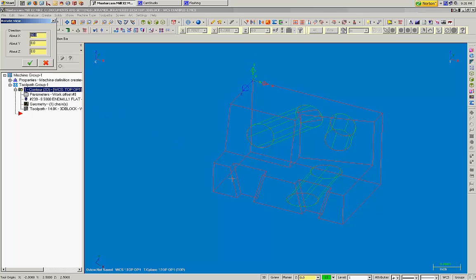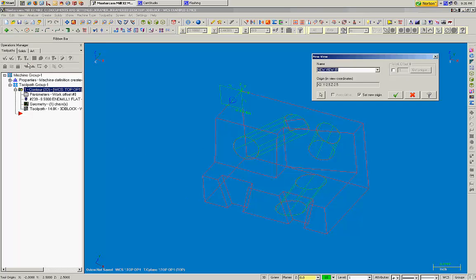That looks good. Now I'd like to have this back wall back here rotate around so the part actually sits like this, and make this my upper left hand corner. So what I'm going to do in that case now is go ahead and rotate around Z 180 degrees. So now this will make this back wall my positive Y, this wall my positive X, and this face my positive Z. Go ahead and say OK.